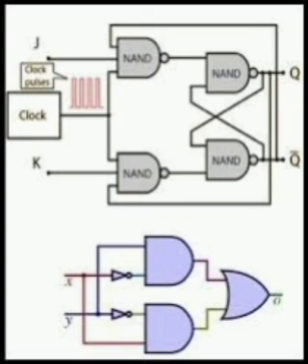The JK flip-flop is called the universal flip-flop because flip-flops like D, SR and T flip-flops can be derived from it. S equal to JQ bar, R equal to KQ. Here 00 is the hold state, 01 is the reset state, 10 is the set state, and 11 gives Qn bar, which is called the toggle state. Characteristic equation: Qn plus 1 equal to JQn bar plus K bar Qn. Race around condition: it will occur when J equal to K equal to 1.